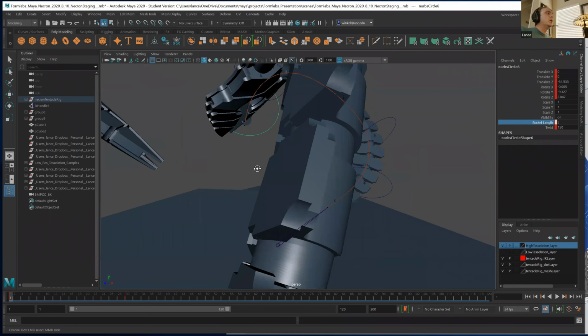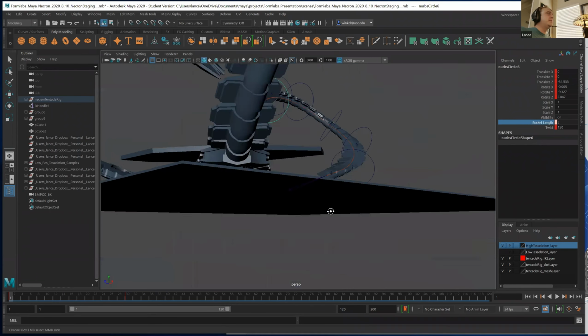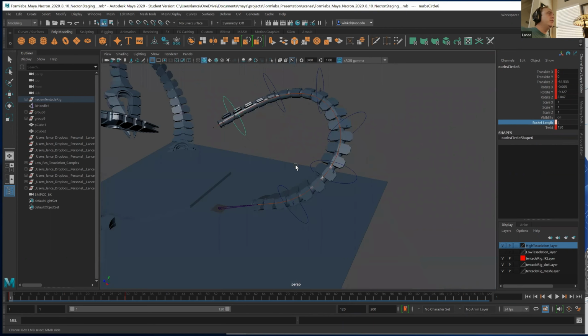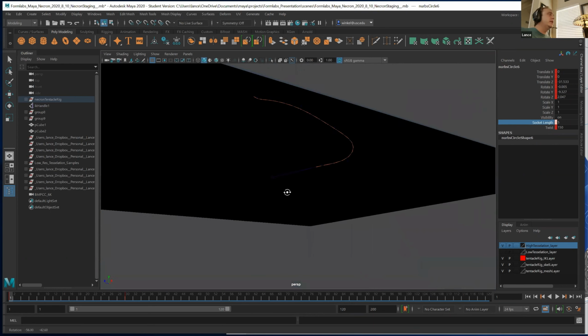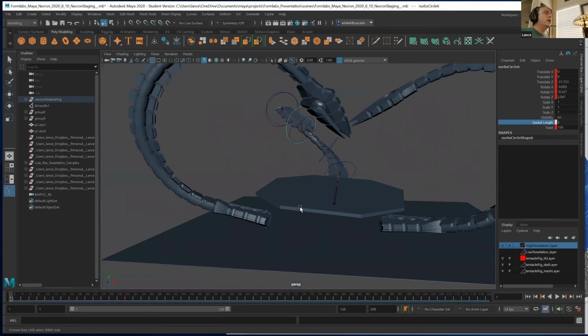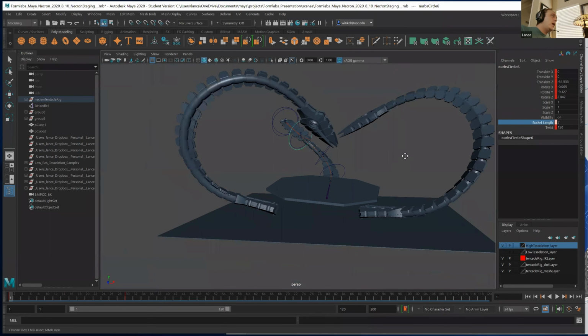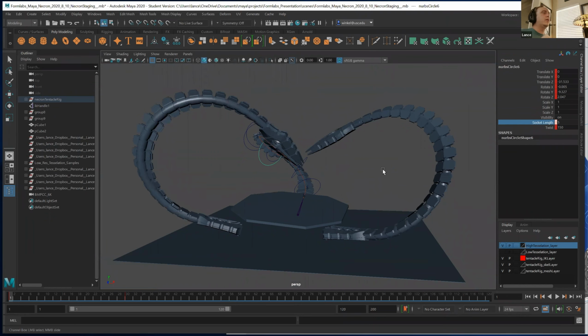Now, once you get something like this set up and staged, and you've got all your setups and everything ready to go, then you want to actually export. We're going to see what that process of exporting is. Maya has several really powerful exporters. Since we're talking about Formlabs and the Preform software, the two main formats you're going to want to export to would be either the OBJ format or the STL format.